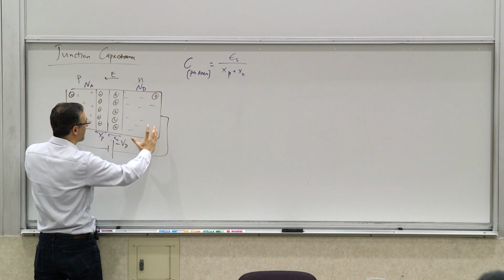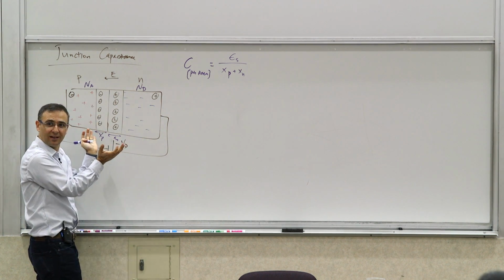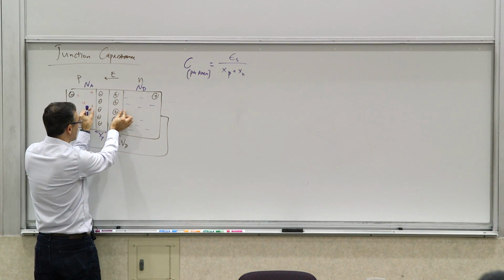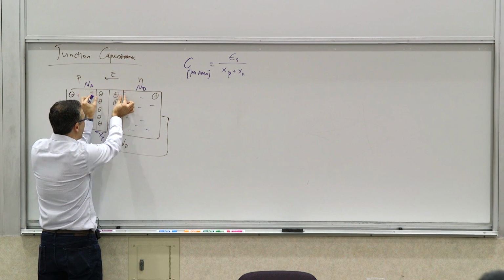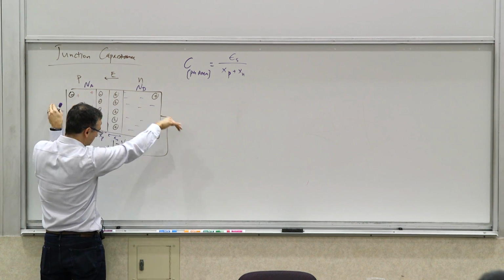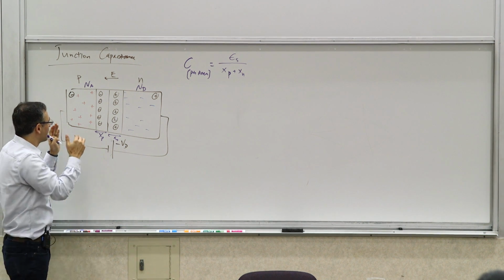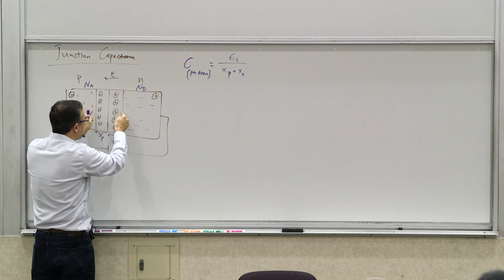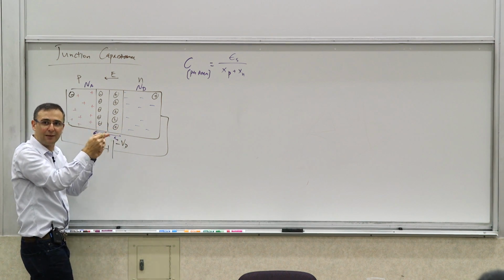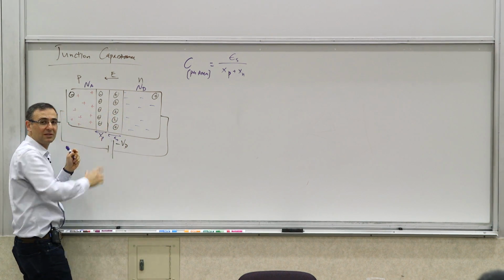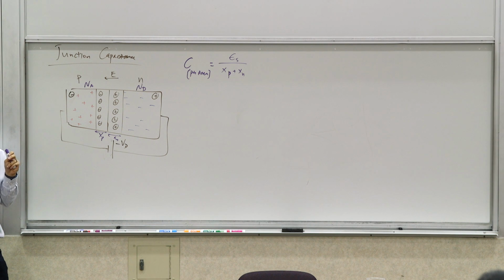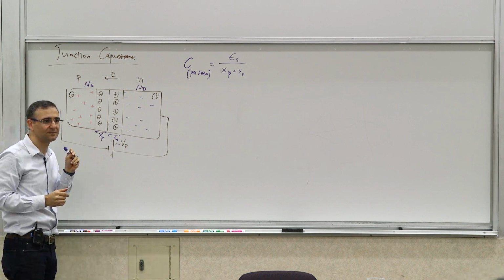So from a black box perspective, it will look like a capacitor, because the charge at this edge is being pushed out or brought in. Since it's the charge at this distance, that would correspond to a capacitance with that spacing of plates. Okay? Does it make sense?